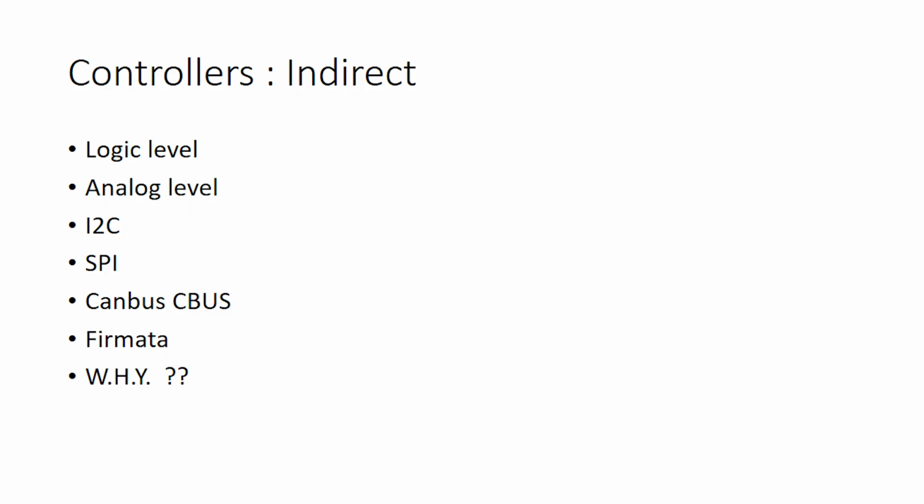These are things that you can use to drive the other inputs on your Arduino or your Pico or your RP2040 or whatever it is. Analog level. You could, for example, put a potentiometer on, and the potentiometer drives the speed at which the traffic lights change on a piece of road. If you've got traffic lights and you want them in demo mode where they're all flashing, but you want them to change more subtly, you could do that.